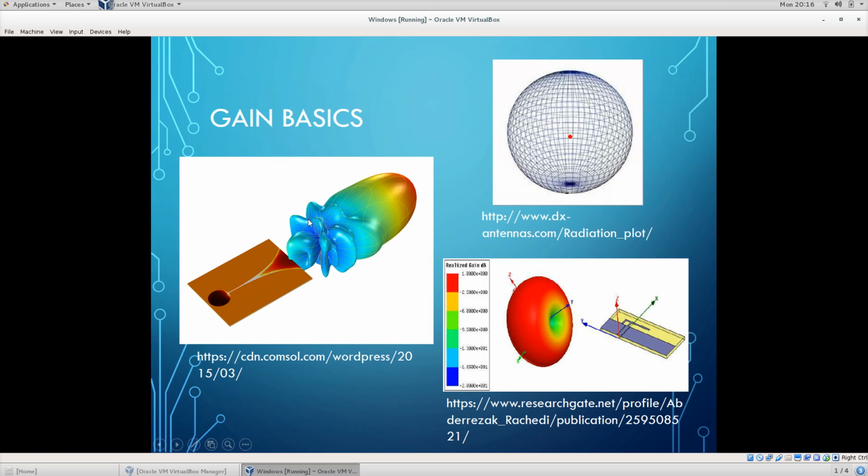So, remember I said earlier that gain of an antenna is kind of an important concept? Antenna gain is different than the standard gain you get in most other electronics courses. Specifically, antenna gain doesn't mean that you're actually adding any energy to the system at all. As a matter of fact, what you're doing is just preferentially sending energy one way versus another.